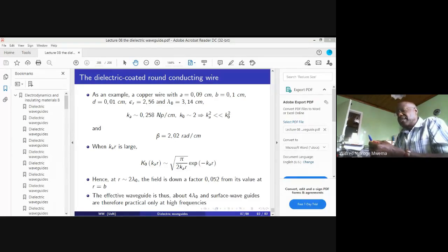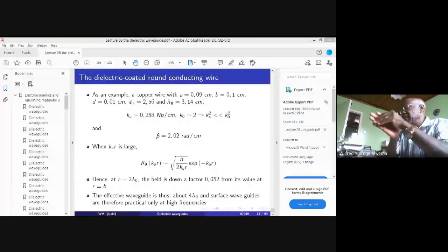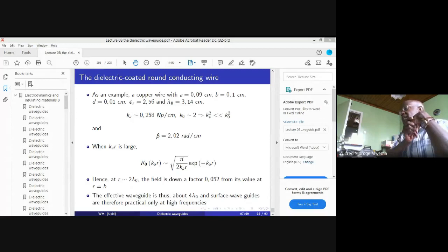Okay, fine. So that capacitive impedance can be written as minus j over omega c. But when you look at this capacitive surface that we have looked at in a dielectric, we are seeing it as minus j multiplied by omega and multiplied by the other constant. So if we were to put the minus j aside, of course it looks like an inductive impedance. But it's not an inductor, because it has a negative impedance. And the only thing that we know has a negative impedance is a capacitance. So do we see the anomaly?